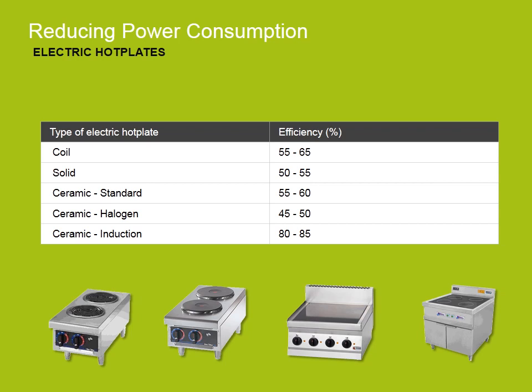Solid electric hot plates are fixed to the hob, which allows for easy cleaning. They are less efficient and have a slower response time than coil hot plates. Due to the fact that they retain heat longer than coil plates, they can be switched off prior to finishing cooking in order to save energy. Auto-sensing elements will assist with temperature control, and sintered elements give faster cooking times. One thing to keep in mind is that they need to be regularly cleaned to maintain their efficiency.